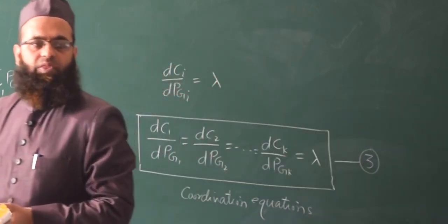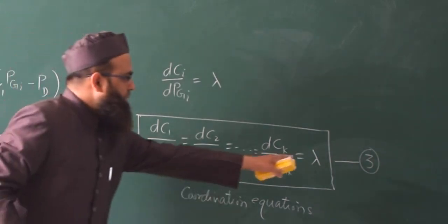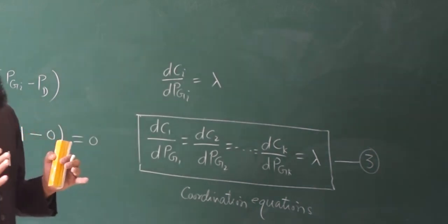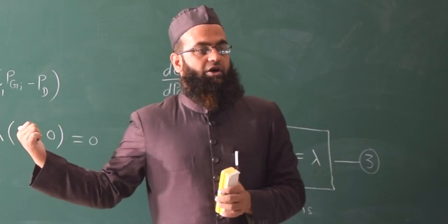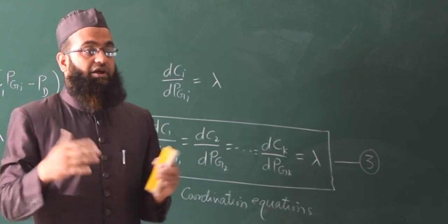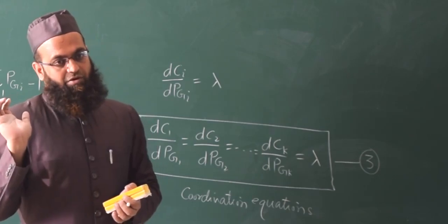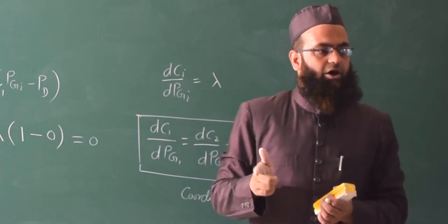For the second unit you are having different input-output characteristics. So for lambda equal to 1.5 you will get 1 point on that curve, is it not? Corresponding to that point you will get 1 PG. So these 2 PGs are suspected to be optimal. Till now we have just taken the necessary condition for solving that classical simple problem f(x). So f'(x) equal to 0 doesn't confirm that you are getting the minimum at that particular critical point. Next check is the sufficient condition, that is the double derivative for a single variable optimization problem.